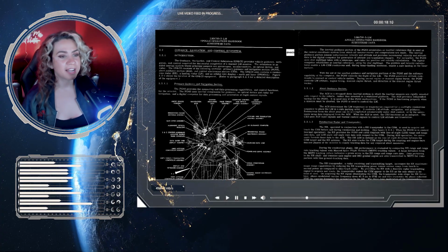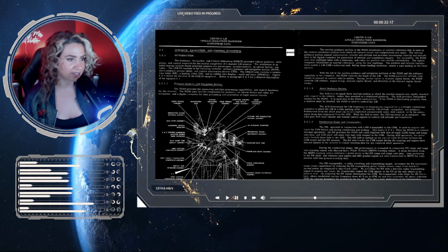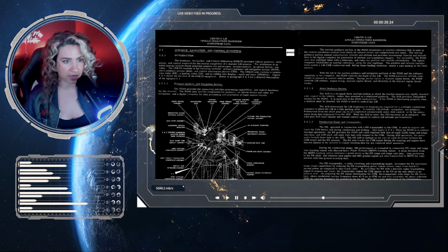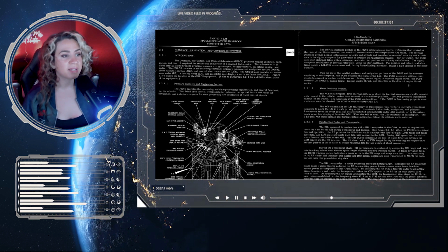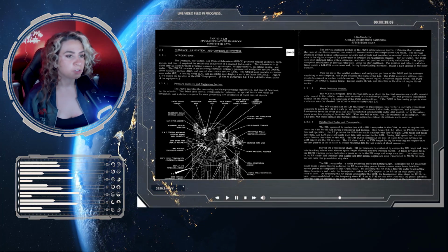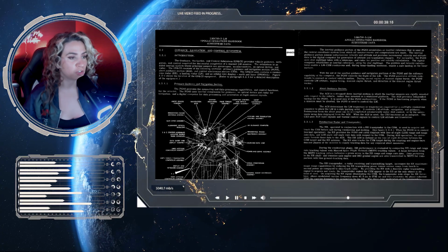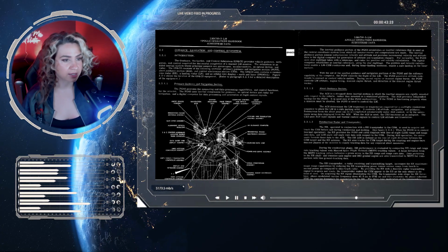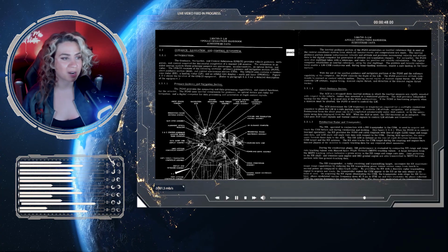When the PGNS is in control, normal operation, the RR provides the PGNS and cabin displays with a line of sight (LOS), range and range rate data, and LOS angle and angle rate data with respect to the CSM. During AGS operations, an astronaut furnishes these data to the AGS. The RR LOS is defined as the line of sight direction between the CSM target and the RR antenna.